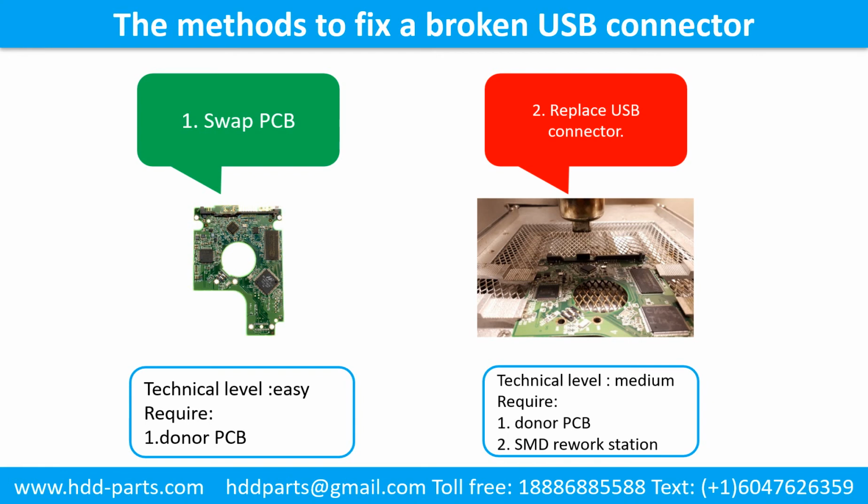This picture shows the common methods to fix a broken USB connector. Method 1. Swap the printed circuit board. Technical level, easy. Requirement, the donor board. Method 2. Use the SMD rework station to fix the broken USB connector. Technical level, medium. Requirement, 1. Donor board, 2. SMD rework station.